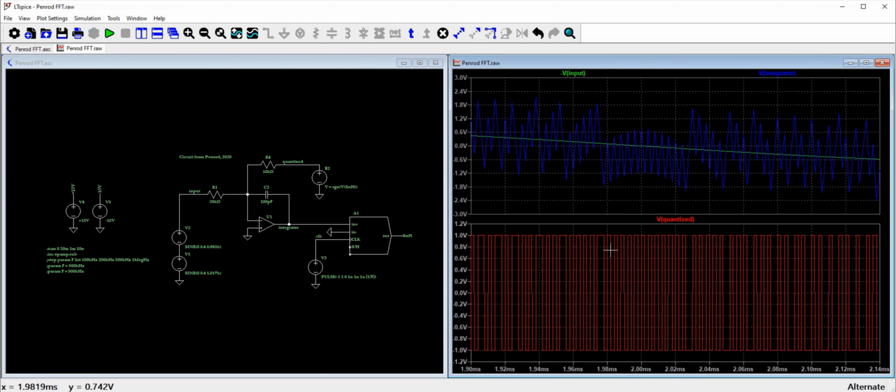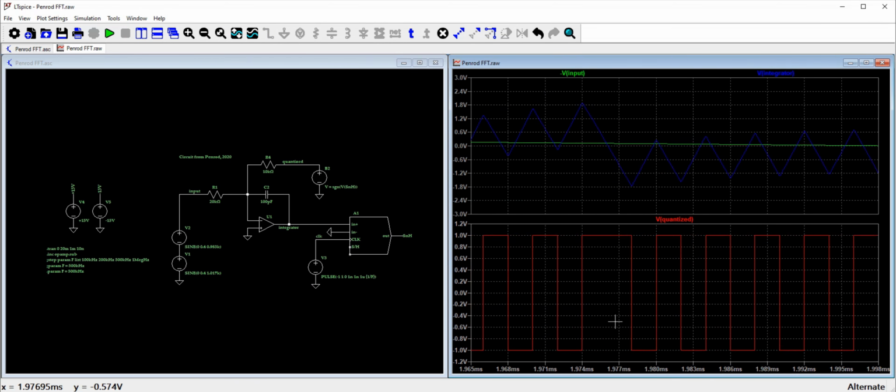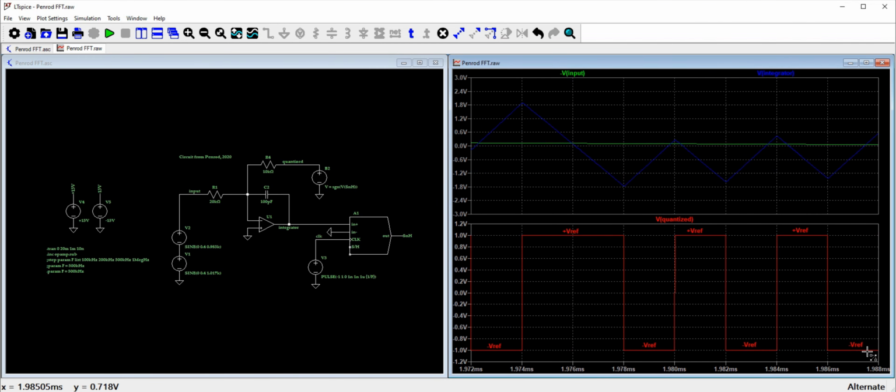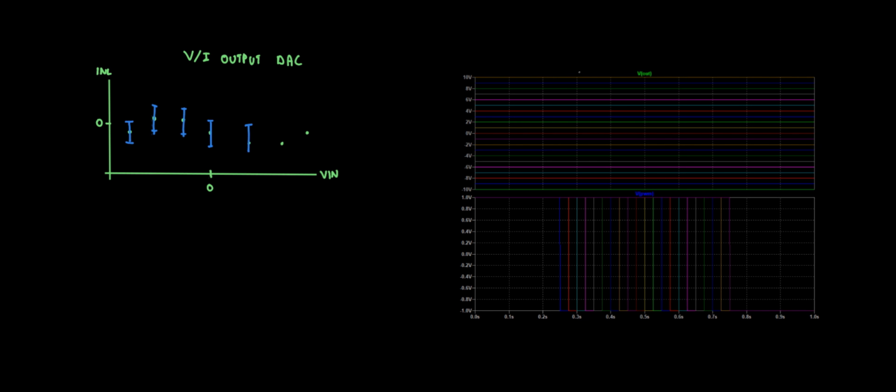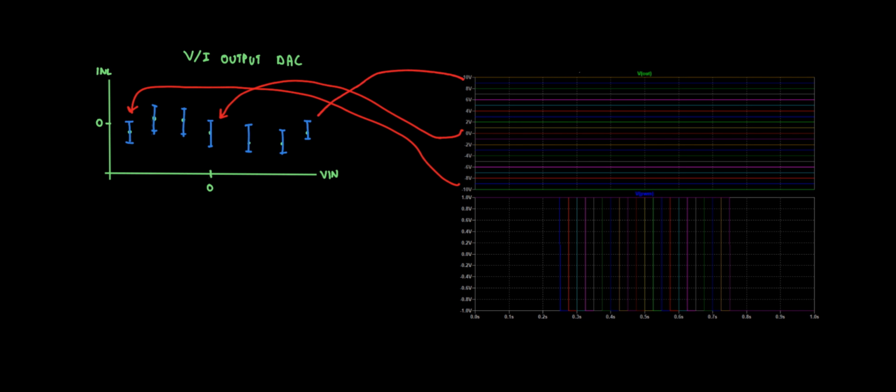In the case of 1-bit feedback, since there are only 2 feedback levels, linearity is theoretically perfect. In a multi-bit system, more exacting requirements are placed on the DAC, which should ideally be both highly linear and fast. Multislope 4 fulfills both requirements by using a PWM DAC. Multi-bit feedback is achieved while also having just 2 levels, maintaining nearly ideal linearity, which ultimately depends on timing accuracy.